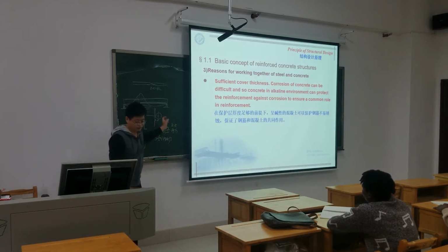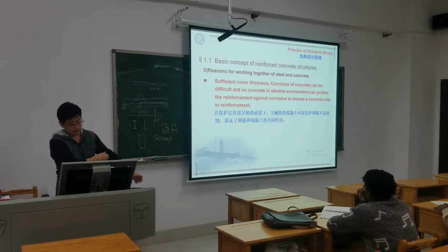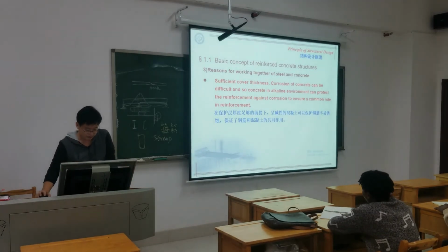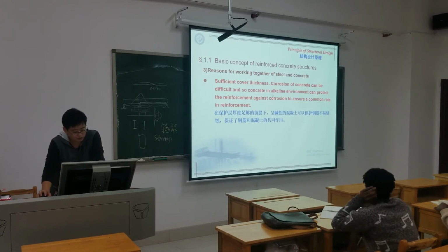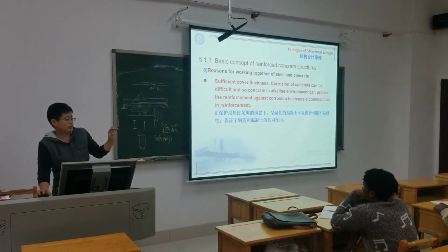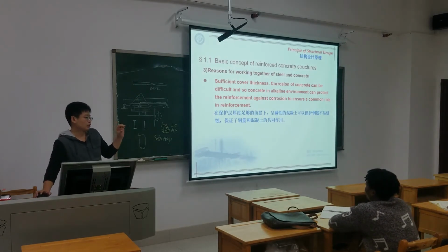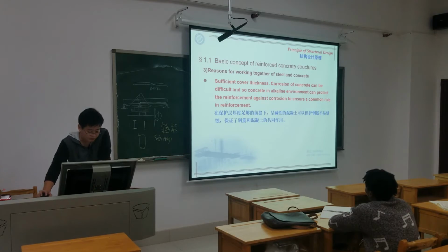So the different shapes of block just make sure there is enough concrete thickness to protect the steel. Such cover thickness makes the concrete hard to carbonate and alkaline. So under this situation the steel will have good working condition. It's not easy to be corroded. Protect the reinforcement against corrosion.